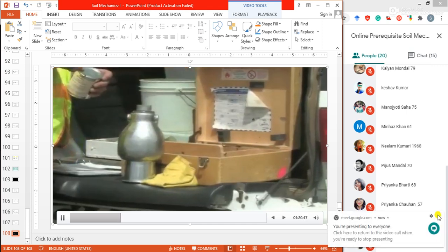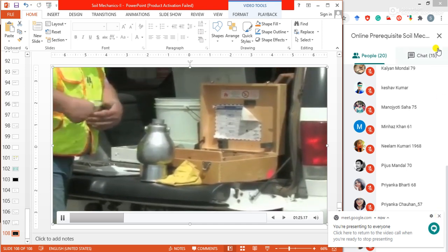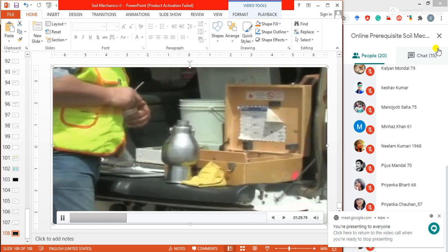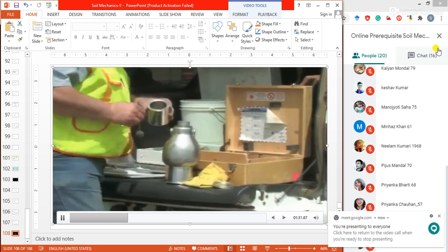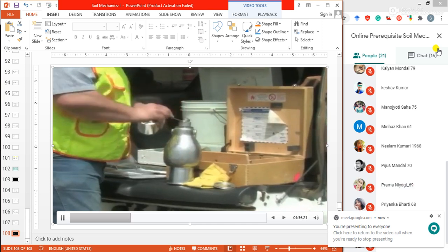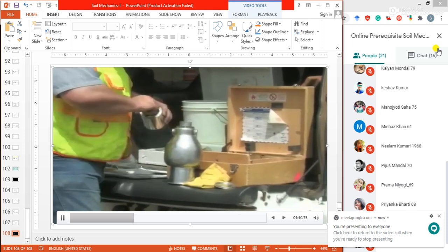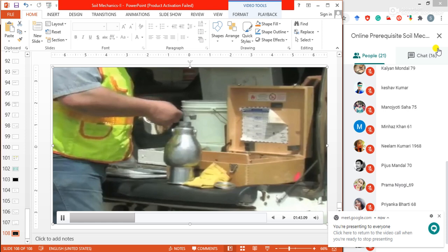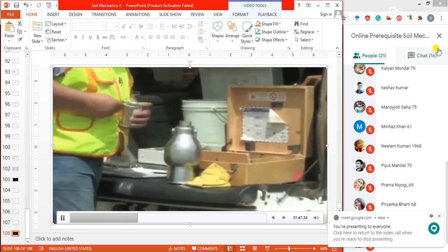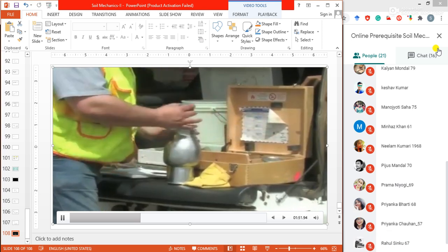The next step in the speedy moisture test is to add the necessary amount of reagent. It is important to keep the reagent separate from the soil sample. Once the two are combined, a chemical reaction starts. The cap of the speedy moisture tester is inverted and placed on the end of the tester. Using the metal scoop, place a minimum of 3 full scoops of reagent into the cap. Make sure the cover of the reagent is immediately placed back on the container and securely tightened.